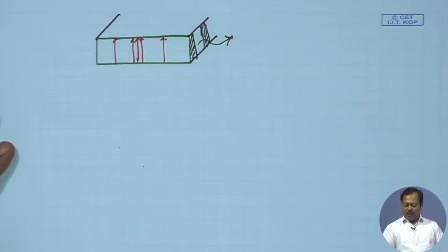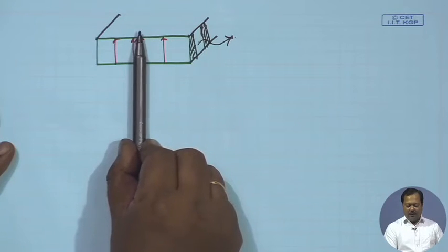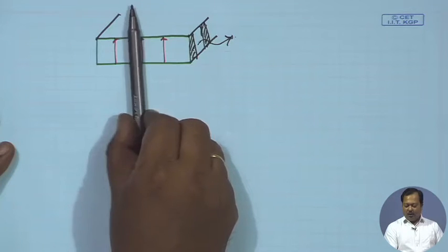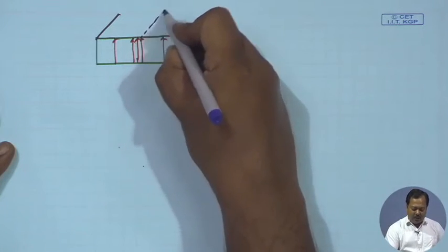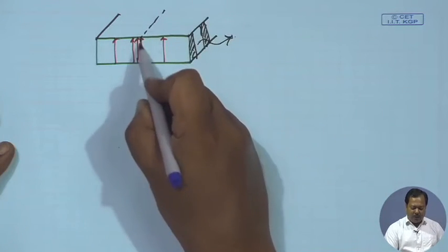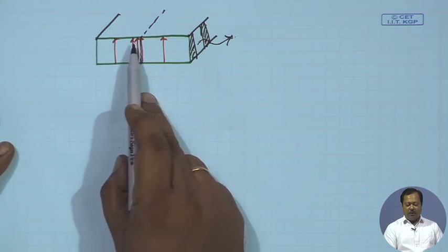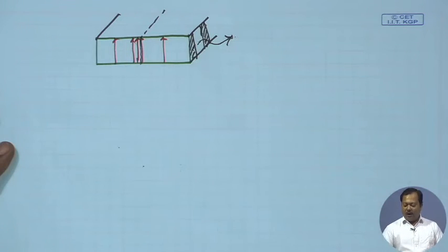Another possible scenario: we see on the mid plane the electric field is perpendicular to the mid plane. So, that means we can place one magnetic wall here or open circuit here, even then it should support a waveguiding mode, or it will work as a guiding structure.